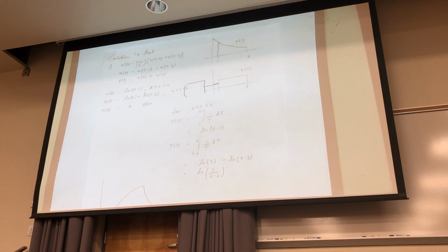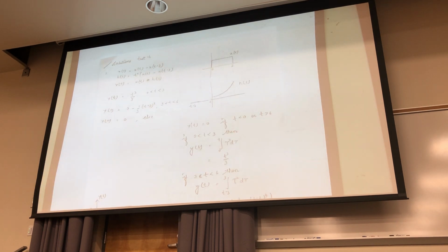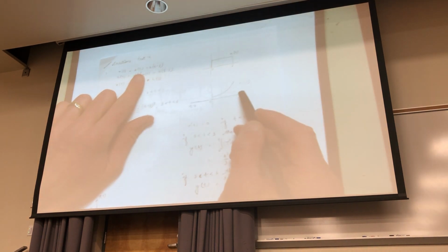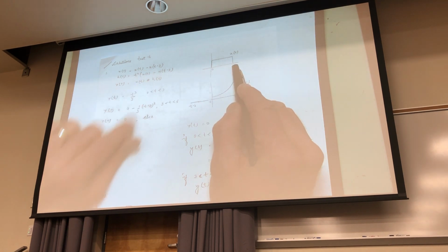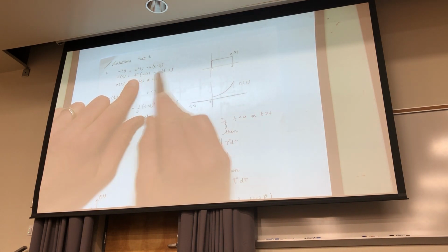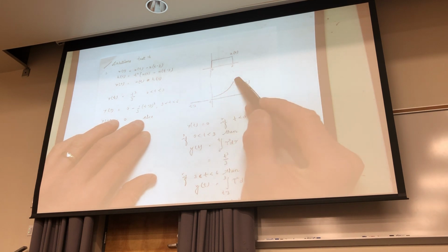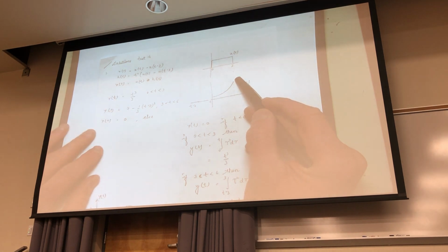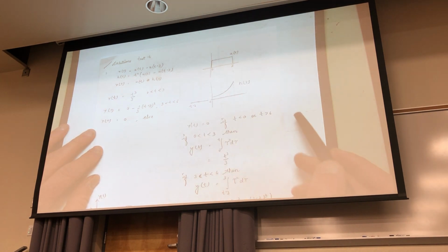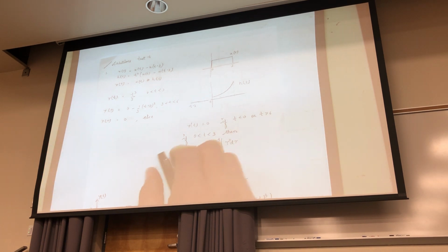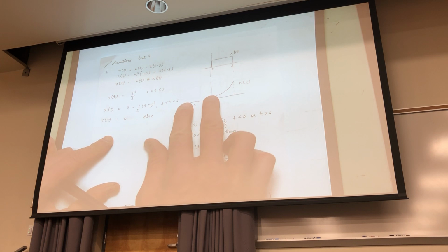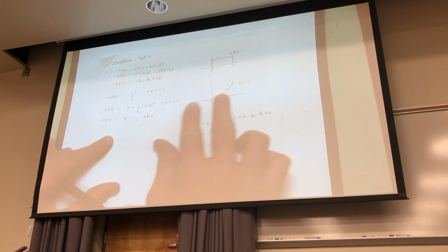The second problem on test B was this one. And it was simply a function where you had x of t times, or minus x of t minus 3, this. And then you had t squared times u of t minus 3, which is this, or t squared. So here I'm going to flip this one and shift it. And when I do, I wish I had a small little rectangle. But basically when I flip that, I'm coming here. It starts at 0. As I shift, I'm integrating through.